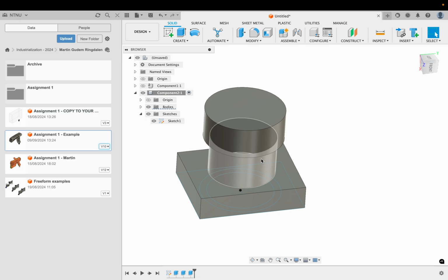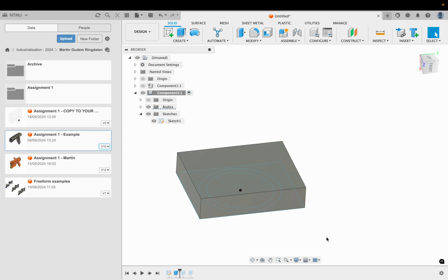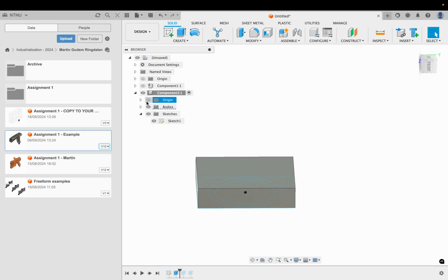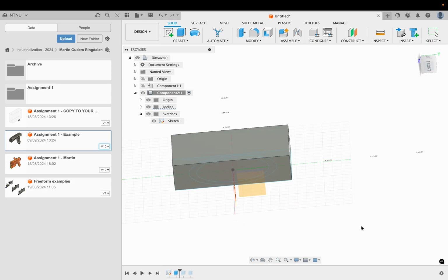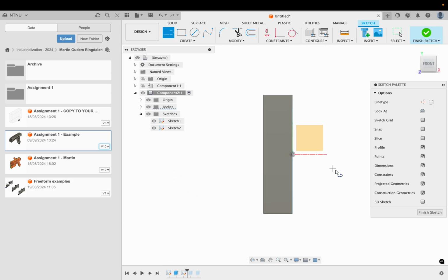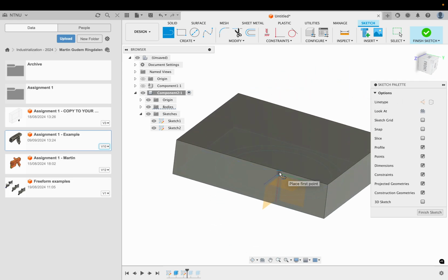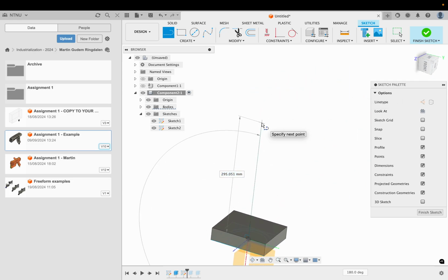And whenever you are making, let's say, a screw tower or anything, if you end up in a situation where you do one extrude with one profile and then you do another circular extrude with one profile, don't do it. It's a lot better to go back. And then, of course, the cost of this is that I will have to do another sketch, but it's still worth it. If I do another sketch like that, it keeps locking me in for some reason. That's a setting that I need to fix. So then you make an axis, and then you make your revolve profile. And then you can do multiple things with that profile.